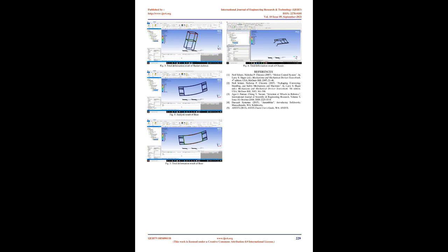Insights. Problems faced while deciding the mechanism of the robot. Deciding which mechanism to go with, conveyor belt or the one with robotic arm. How to stop the ball coming with a velocity of 4 m/s or in a projectile. How to take the ball to a height of 300 mm, meaning whether to keep the conveyor belt vertical or keep it on inclination.